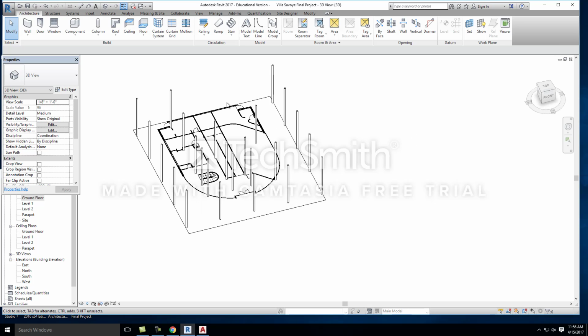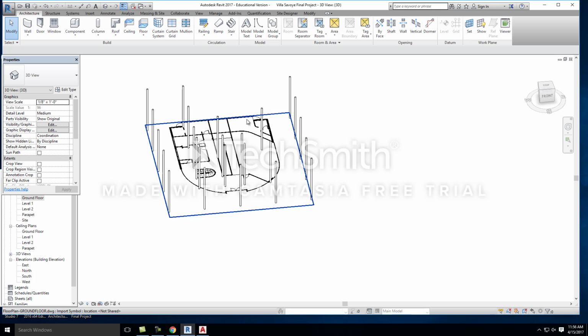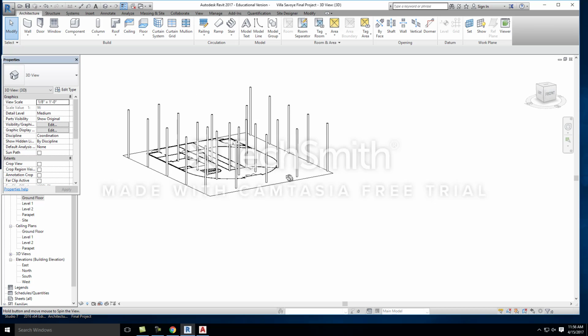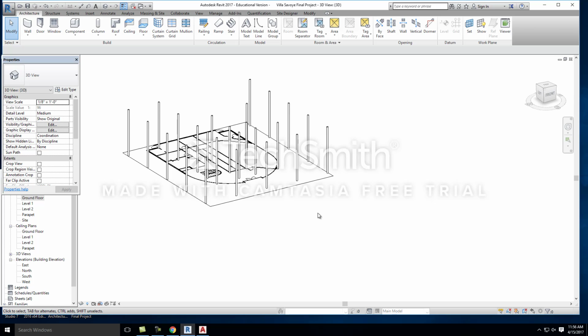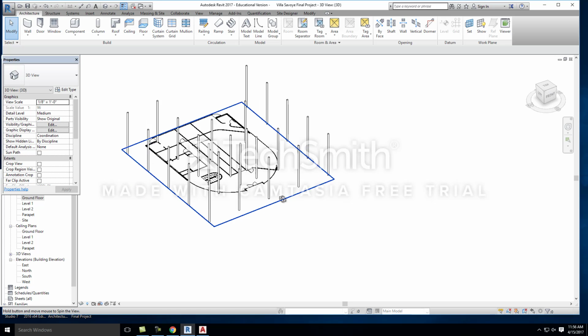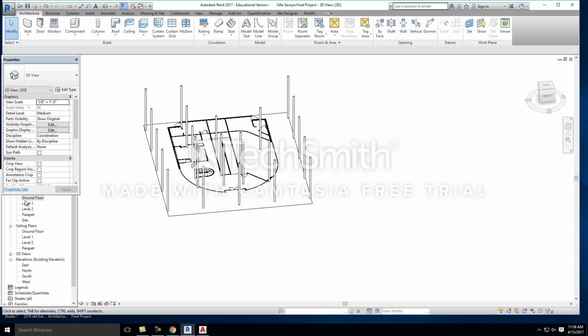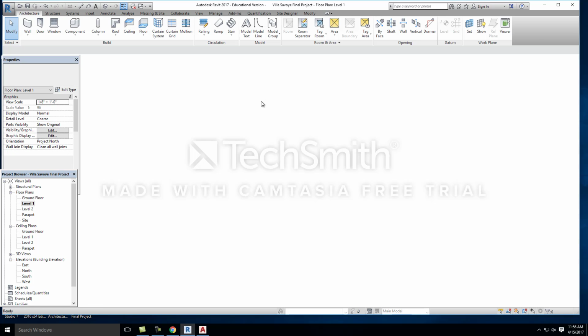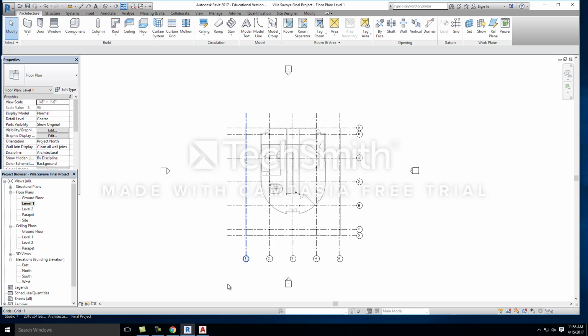You can see here that, minus probably a couple that would be over here in the back, we kind of have the basic grid system, the basic structural framing of our building. So there's going to be all of our columns, or a majority of our columns. The next step is going to be to create our different wall assemblies. For now, we're going to create the ground level.